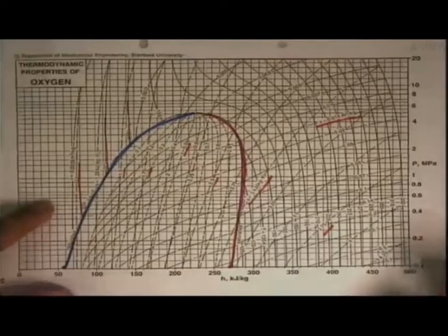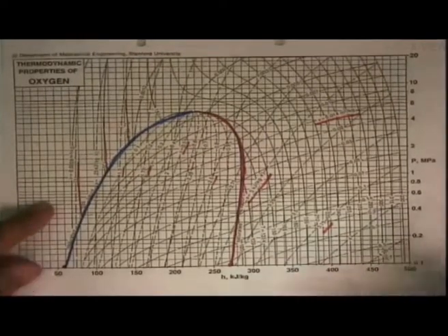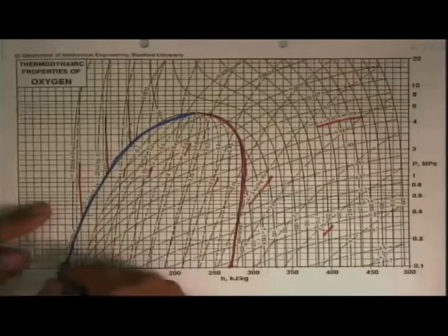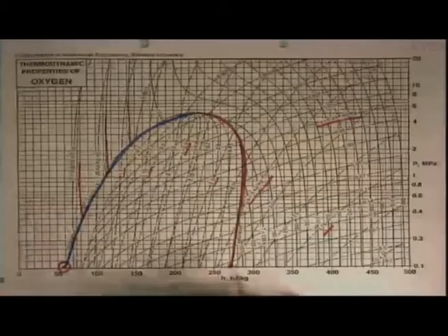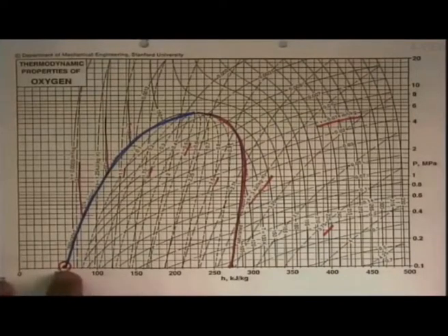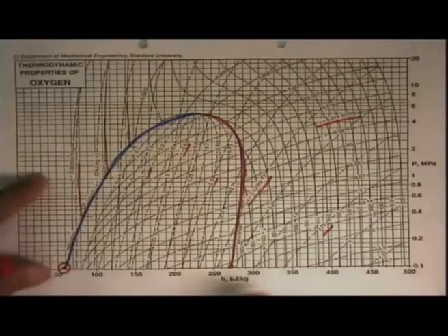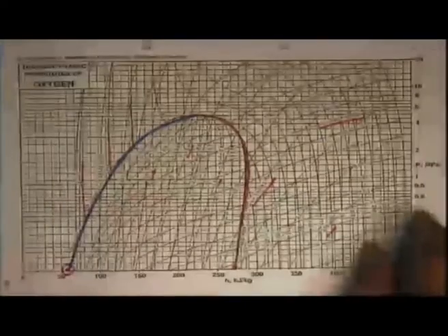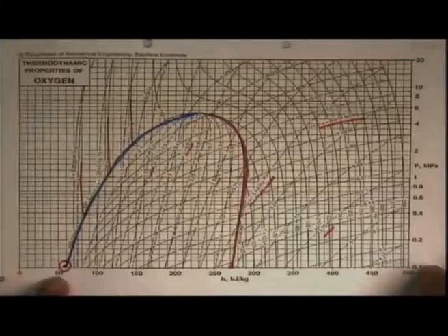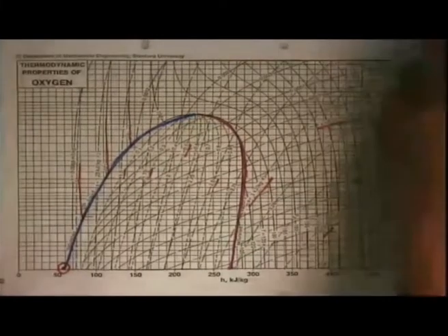And the reason for saying this is that in the cryogenic engines, a picture of which I showed you yesterday, the oxidant is liquid oxygen, which is filled at this state. So we need to know what is the specific volume there, how sensitive is it to temperature, what is the specific entropy, what is the pressure and temperature to which I need to cool it, and then we know how much volume we need to have in the rocket motor to put that much liquid oxygen in it. There are many other uses of oxygen.